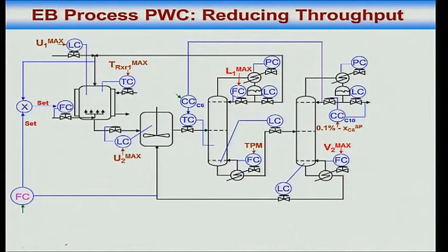If V2 max is kept at V2 max, what that means is boil up is large, therefore I am boiling it up. To not allow the diethyl benzene to leak up the top, I will have to reflux more. Yes or no? So I am unnecessarily recirculating things here, and I am wasting steam. Yes or no? Okay, so once the throughput has been reduced sufficiently, I will take up temperature control whenever I can, of the stripping tray.